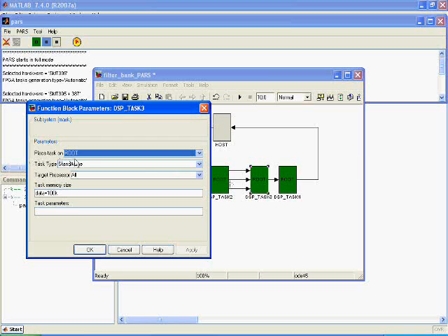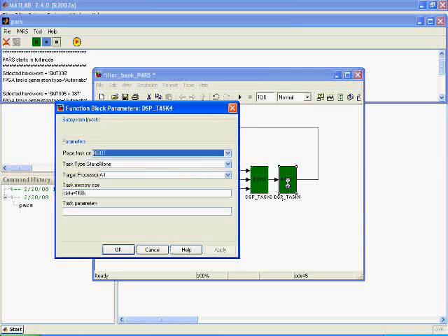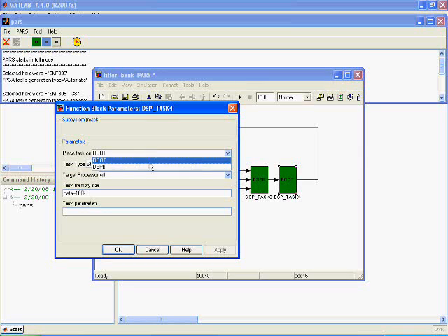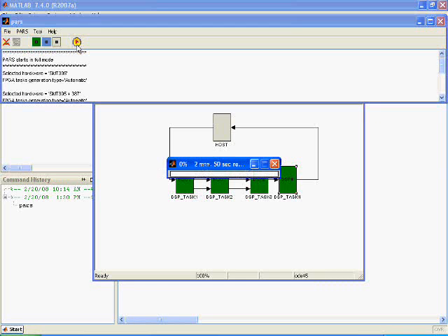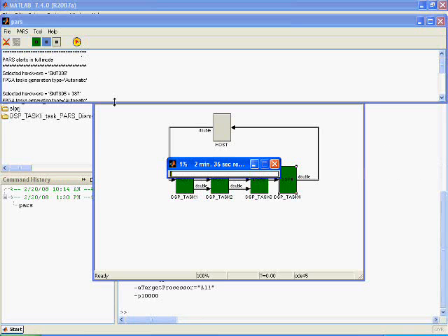Double-click on the 3rd DSP task and the Properties window should open. Go to the Place Task On and from drop-down menu select DSP-B. Click OK and then repeat the same for the 4th task. Save the changes and press the yellow button in PARS to generate the code. The magic begins and an entire application targeting 4 tasks to the embedded multi-DSP system will be created.